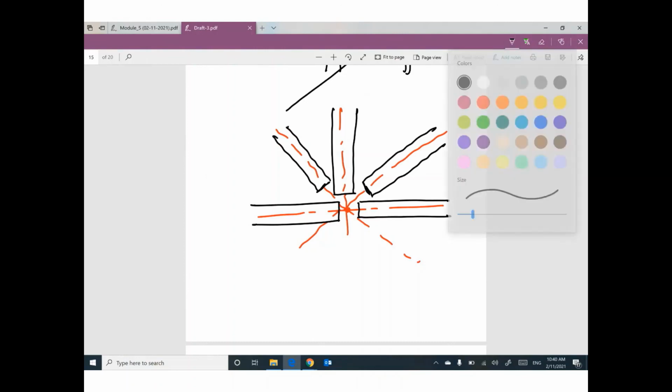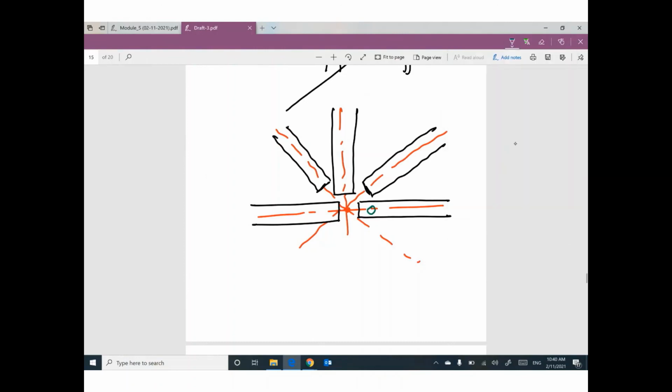Once you are done, go ahead and put your bolts based on how many you want, and then the edge of the gusset plate like this, vertical. It's not a vertical line, it's a line perpendicular to the member itself.